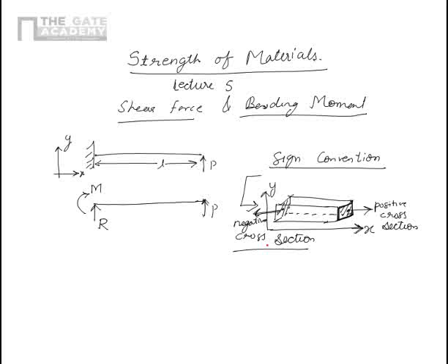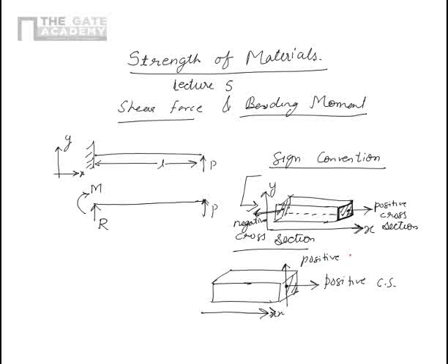Now the convention is like this. If we take the beam again here, this is a cross section, and because this is the plus x direction, this is the positive cross section. The shear force which is acting in positive y direction on the positive cross section, this is the positive y force.